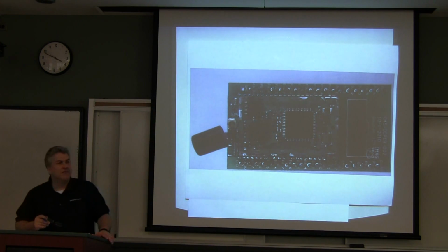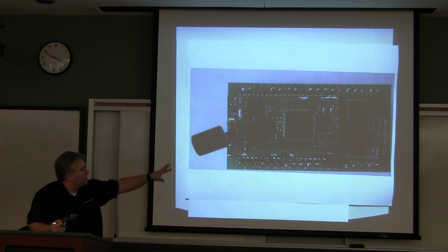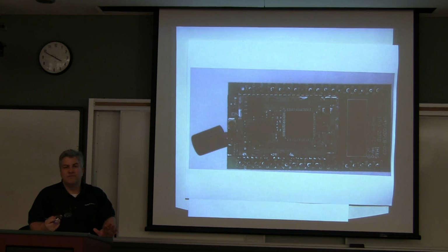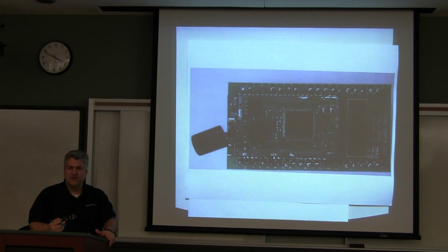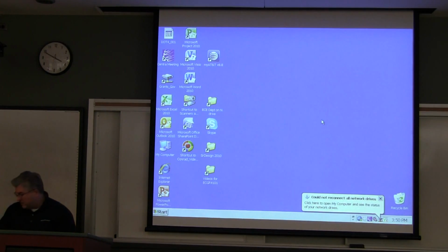But usually, if you take anything, let's say your old cell phones, and you open it up, hardly anything goes through the board. That's the old DIP parts, meaning dual inline package, or any other larger parts like capacitors that you don't want to go through the board because it's harder to manufacture. Something surface mount like this is really easy to manufacture via automated machinery. Have I shown any pictures of that yet? I can't remember. Oh, I did that in robotics. So let's open up one really quick and show you an example of that.